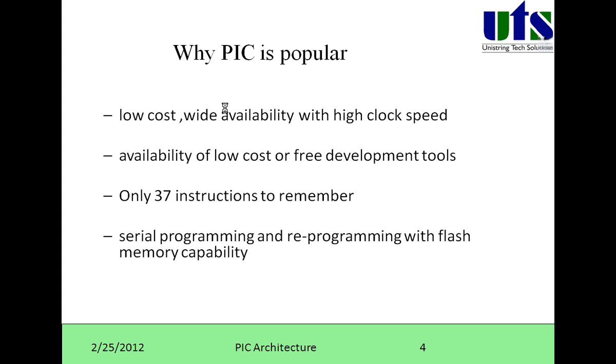If you want to write any program and dump the output hex file into the PIC flash, we can use a serial programmer for programming and reprogramming. That means you can write data to or erase data from the flash by using serial communication. That is, it supports in-system programming.